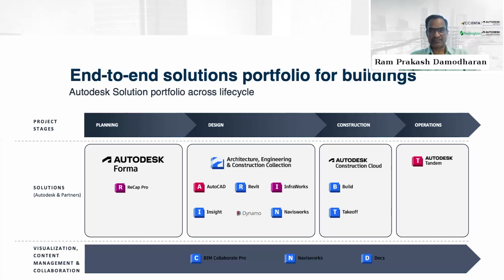So what Recap Pro normally does is create a technology way of scanning that entire site condition using laser scanning, or nowadays you can see a lot of drone cameras also available, and it's going to capture all the area as point cloud data. The point cloud data you use to fine-tune the objects, and you can also derive the model from the as-built as well. That's where you are using the software called Recap Pro, Reality Capture Professional.